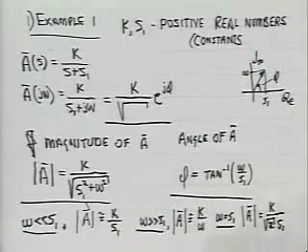So all I've done here is to take the magnitude function, K over the radical, and in two cases, the first two, low frequencies and high frequencies, approximate it in the low frequency case by a constant, in the high frequency case by something which varies as 1 over omega.